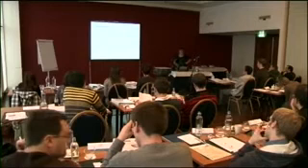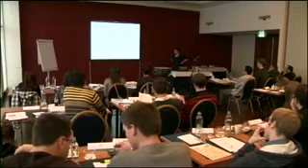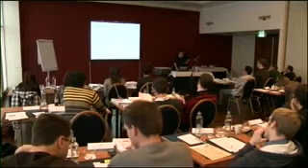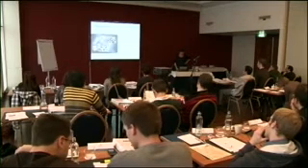that you can use this two ways. If you know the crystal structure, you can determine what the peak intensity is. You can also use it to determine a crystal structure if you've got the peak intensities. We usually generally use it the first way because we assume that we know the crystal structures, and then we use it to determine how much of each of those crystal structures are present.